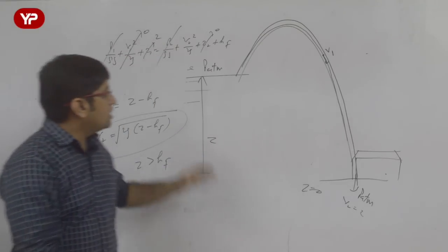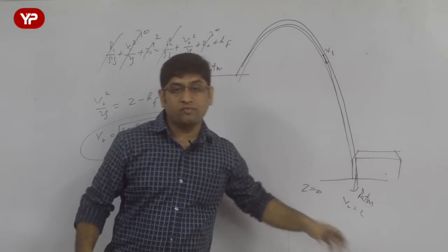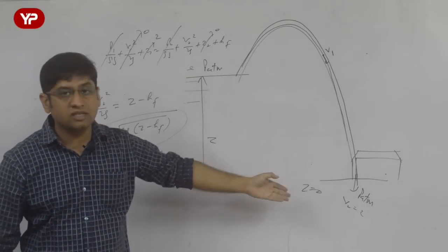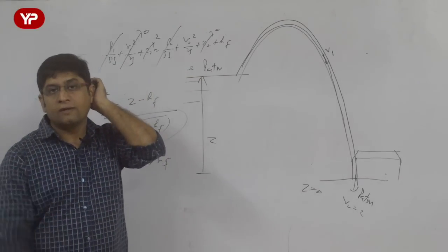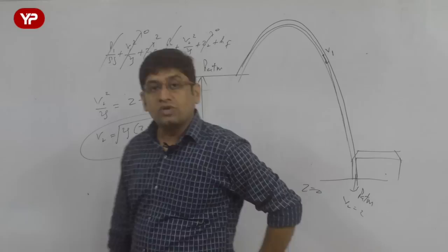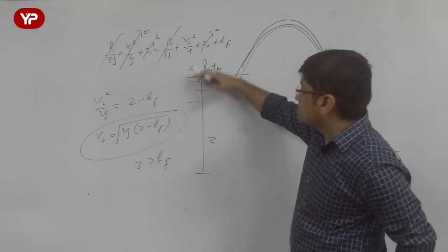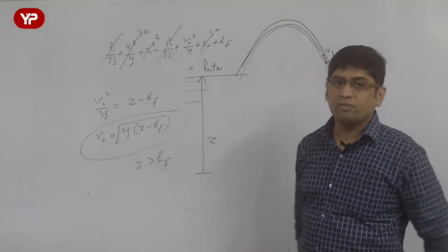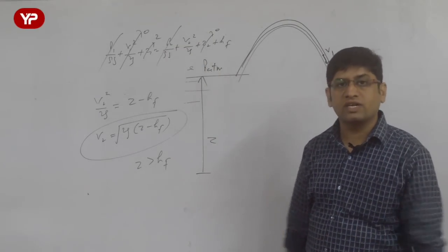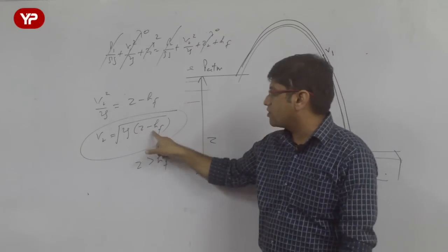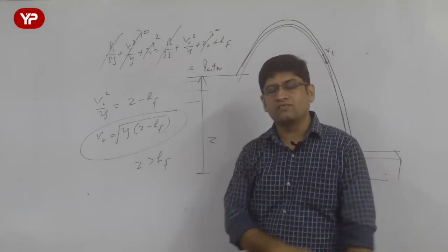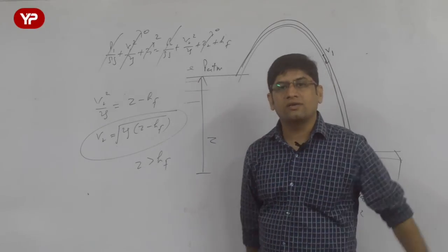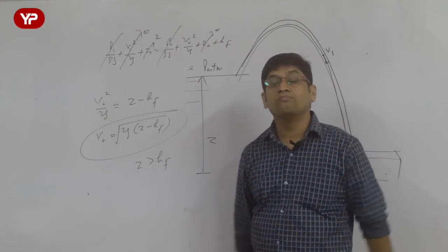So if you lay the pipe, if you're a civil engineer, first you calculate what is going to be the head loss in this. If you calculate head loss, then only will you be in a position to tell whether the head available is more than the head loss or not. If head available is not more, then fluid is not going to flow because of the friction. But suppose head available is far more than head loss, then obviously it is a very good thing for us. We can get water if we lay the pipe across the mountain.